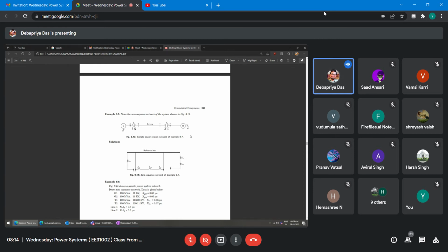Here, in the motor case, Zm0 is there, the motor reactance, and here you also have one neutral grounding reactance or impedance. So 3Zn we have seen earlier, this is 3Zn, and this side is also grounded, and this side is delta. So this side is connected to the reference, and this side is open, that is the Rx point, which is also open because this is delta.